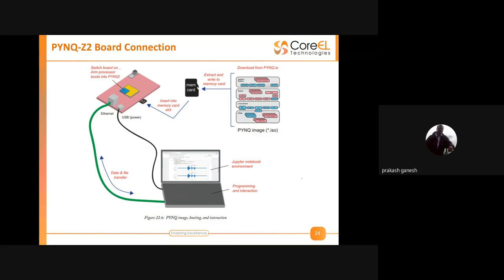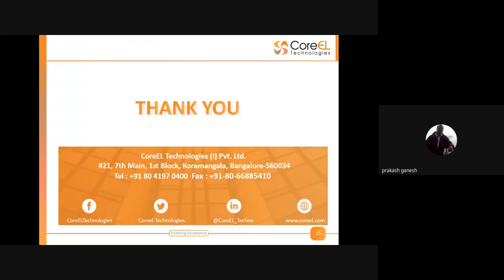So this is similar to having a single board computer. Instead of having a processor computer, I'll be using an external board here. I'll be inserting that SD card into the SD card slot and connecting the USB power cable to check whether it's booting properly or not. I'll have the Ethernet communication also, because if I want to download some packages, I can use that Ethernet to share the internet from my host machine to the target board. But we need separate interfaces also.